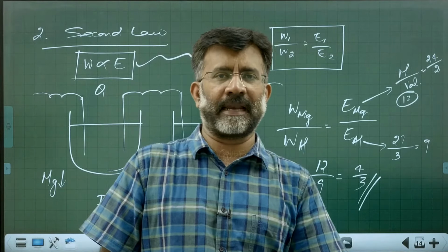A simple corrosion is the rusting of iron. Rusting of iron is explained as a mechanism of corrosion. Right? Here you can find some irregular surfaces on iron metal where some moisture is settled. It acts as a micro electrochemical cell. And there the rusting is triggered at irregular surfaces where moisture is involved. It acts as a tiny cell.